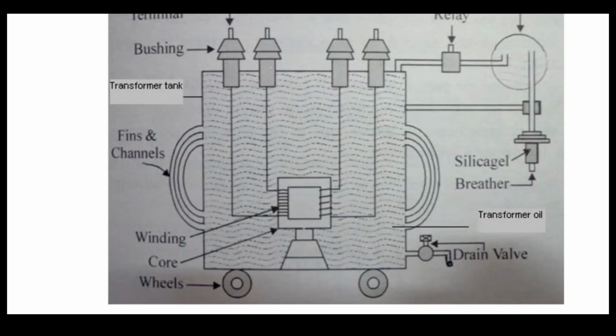Also, between the blue and pink, some light chocolate, brown color is also adopted by these stones. This process continues for many cycles, but a stage is reached when the color of these stones does not change. When the color of these stones does not change, we can realize that the time has come to replace these silica gel stones with new ones and not the reused ones.